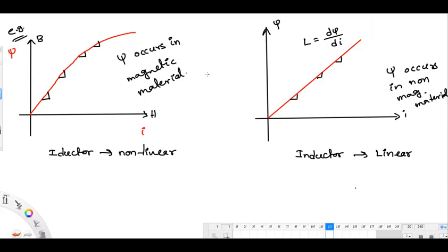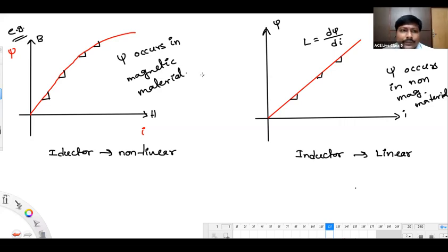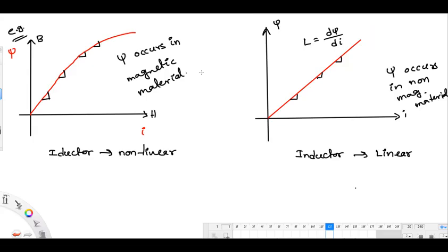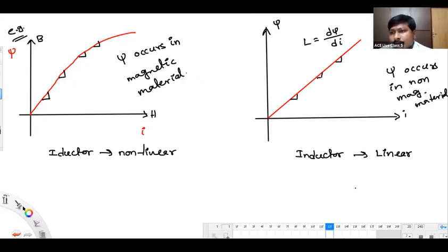Then regarding the ground current in DC single phase, sir, if the conducting ground is an extremely dry area, like a desert where we are setting up this plant, then you have to go to a low depth until we have some moisture. Yes. Even HVDC stations are grounded at a depth of half a kilometer. They will drill half a kilometer and keep the electrode there for perfect grounding, because they have to run kiloamperes of current in the ground. So they will go up to that depth.